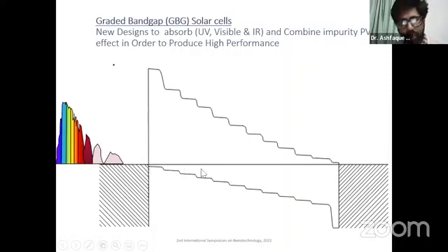And along the way, we can see it's actually transiting from P-type to I-type here in the middle. And then N-type here, the Fermi level is near to the conduction band. So for a graded bandgap solar cell, the basic structure is the transition is not only taking place for the band gap from higher to lower, but also the transition is taking place from N-type towards P-type, or the other way around, from P-type towards N-type. So that is the basic structure of the graded bandgap solar cell.